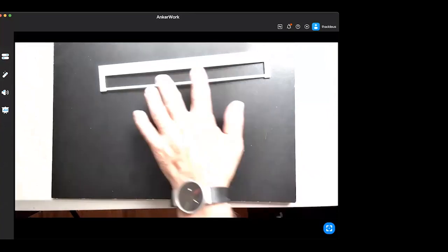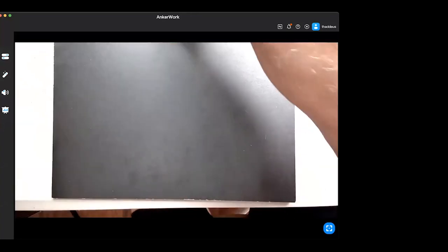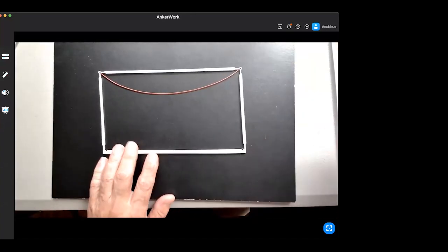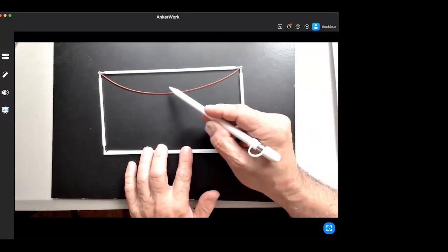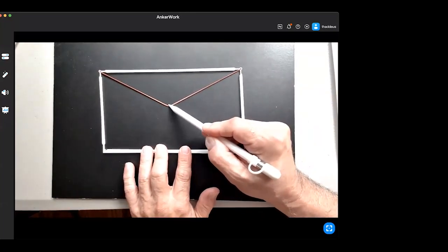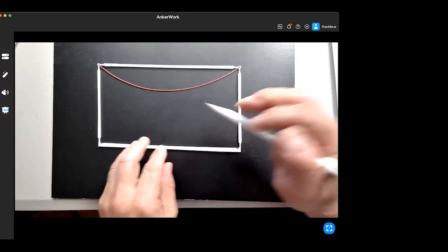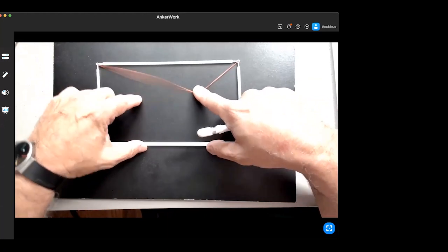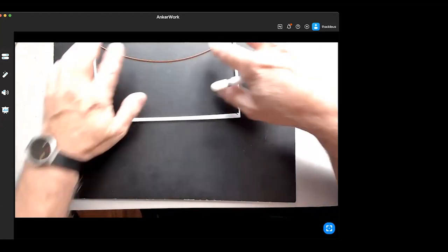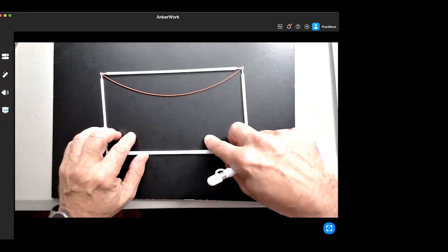Excellent. Just one addition to that. I see when you're deflecting it, the shape is curved, but your diagram showed on a point load that it was a straight line down. Was I just misreading your diagram? No, you were not. Since I have this on, if you imagine a cable and you do it in the middle, you get a point. That's the moment diagram for a concentrated load versus for two concentrated loads. This is for a uniform load. Does that make sense? It's a parabola.